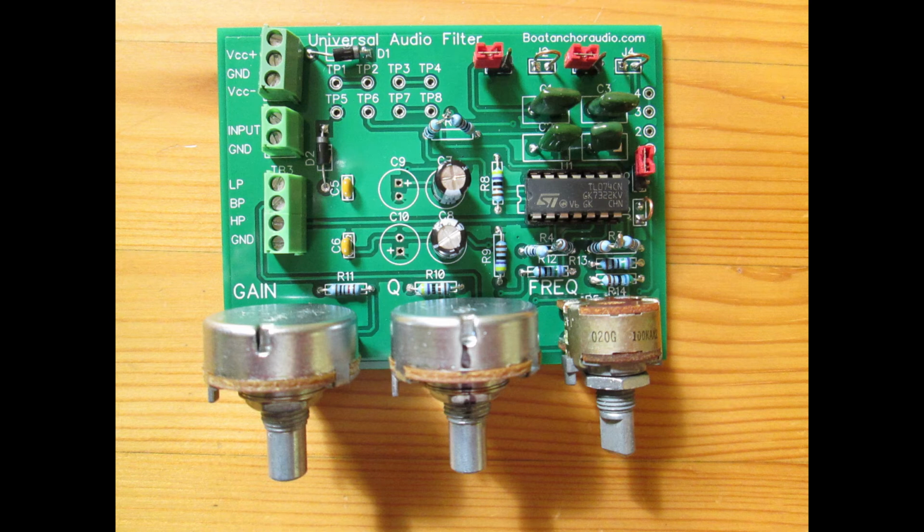The rest of it's pretty cut and dried. As you see, the chip there is a TL074. Yeah, you might be asking why I used a chip that old. There's a couple reasons. One, the 074 has been around the track. It's been around since '78. It's very reliable. You can buy them anywhere. But there's a lot of chips out there. You can buy them dirt cheap. And they're probably dirt cheap for reasons. Maybe they're rejects. Maybe they come out of the recycle bin. Maybe they're counterfeit. For something like this, it's best to go to a name brand supply house, spend a couple pennies more, and get a reliable chip.